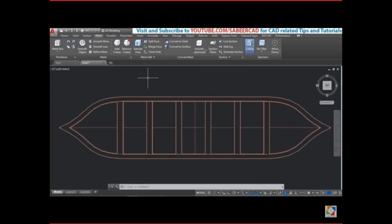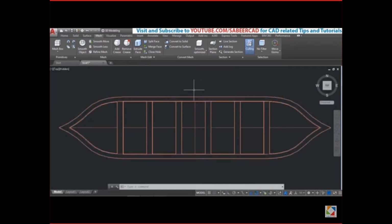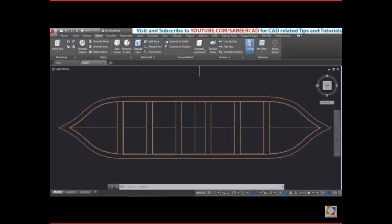When you look at the shape of the boat in the top view, you can see that it's symmetrical about the horizontal as well as about the vertical axis. So instead of creating the entire model, I'll create just a quarter portion, or 1/4 of it. Then I'll give the mirror command to generate the entire model. I'll start by creating this particular profile first.